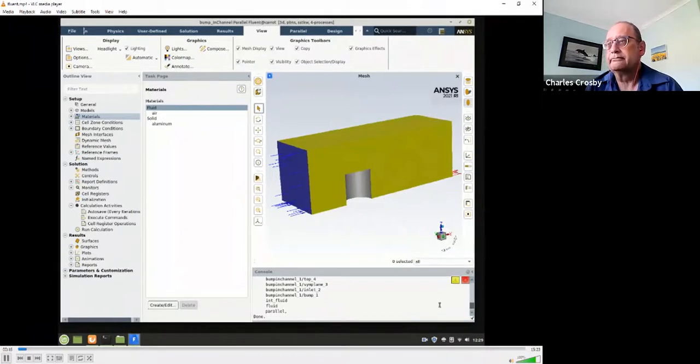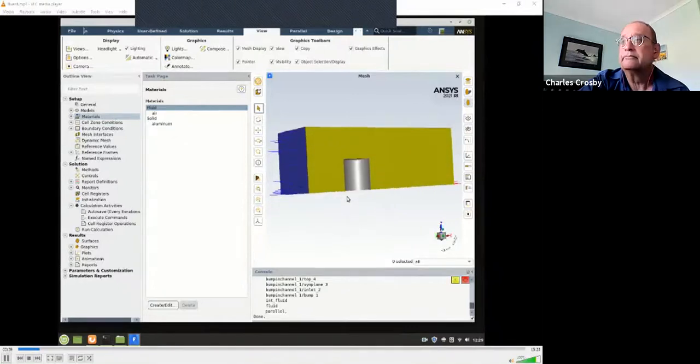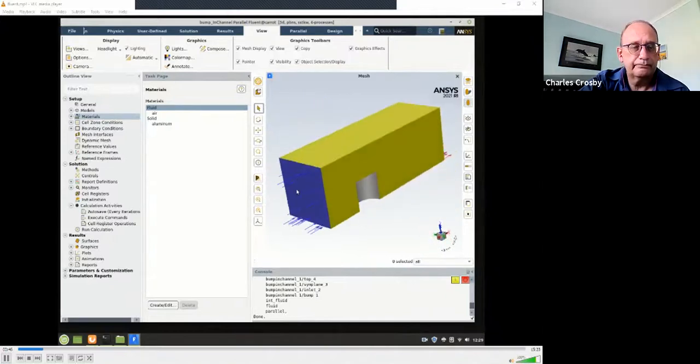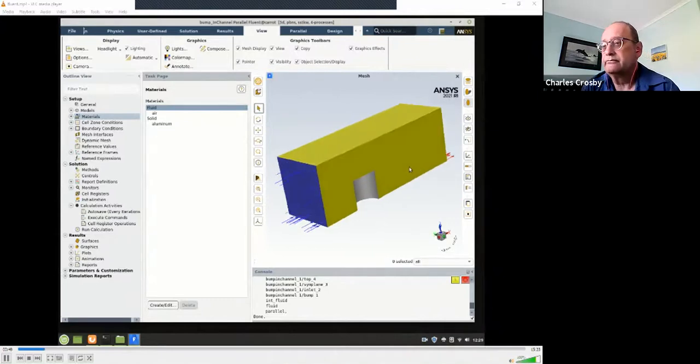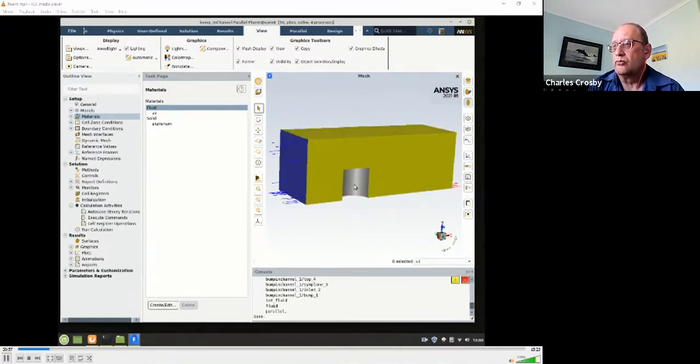You will recall from the mesh generation that I exported the model mesh in a .msh format for Fluent. Now it turns out that .msh files are read by many different types of CFD software, but it's originally intended, of course, for Ansys Fluent. So I've already imported the model into Fluent, and it is shown here. We defined the boundary condition types in the mesh generator, so it already knows that the inlet is an inlet. It's showing velocity vectors going in there, and the outlet is an outlet, and these yellow surfaces are symmetry planes, and the gray surfaces are walls.